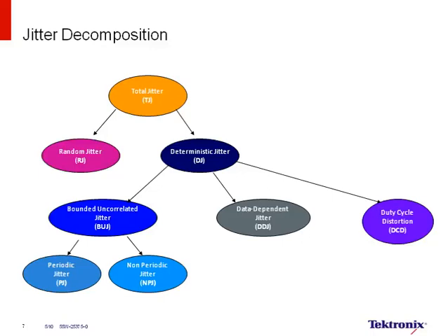The primary cause of data-dependent jitter, DDJ, is intersymbol interference, ISI. The terms correlated and uncorrelated indicate whether the amplitude of jitter changes with different transmitted data signals or data rates. That is, whether or not the jitter amplitude is correlated to the data.